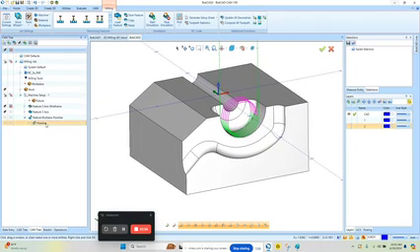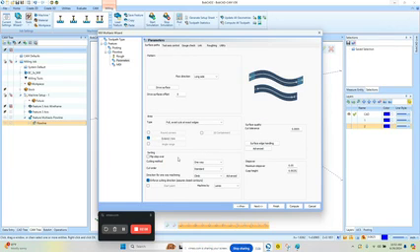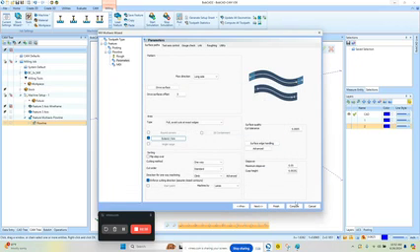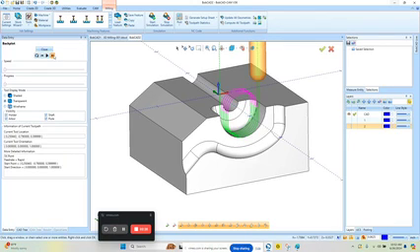Let's go ahead and get into the feature. Go to parameters. We're going to turn on extend and trim. Okay, this is going to be for the ends of the part, so we're going to say 50% to begin with. Okay, we're going to do one of these at a time, so this way we can see the impact it has. So you can see we can use that tangential extension in order to adjust the lead out almost in this example. So we can get it to transition without running right into the material. Okay? All right, so that's that.